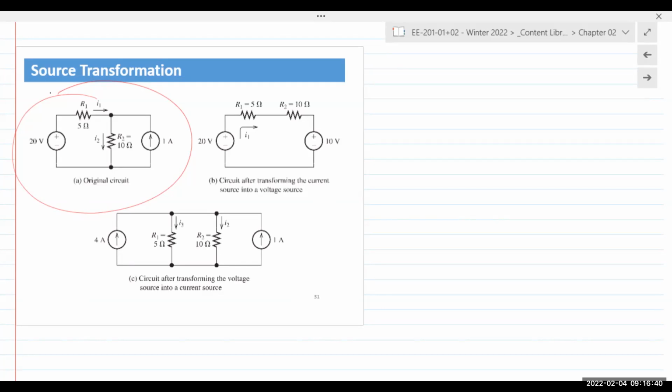So in this case, we have resistor R2 and the 1 amp current source. Both of them share 2 nodes at both ends of their component, right? They're connected together at the top. They're also connected together at the bottom. So we can write that the resistor R2 is in parallel with the current source.